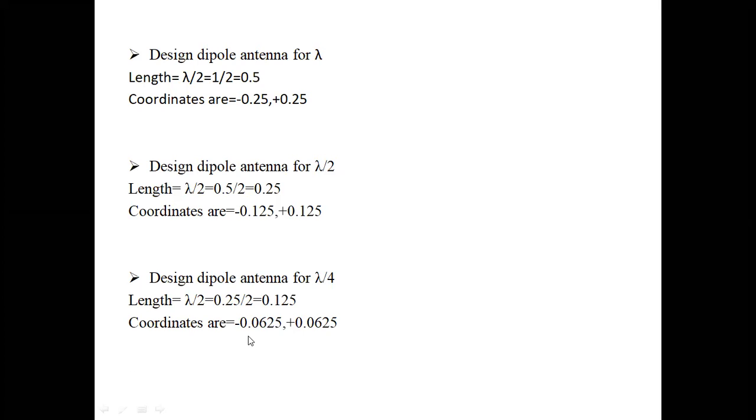Now before moving ahead to drawing it in the EZNEC software, first I'll tell you what radiation or a radiation pattern is. Radiation is the term used to represent the emission or the reception of the wavefront at the antenna and specifying its strength. To represent the radiation of an antenna as its radiation pattern, one can simply understand the function and directivity of the antenna by having a look at its radiation pattern.